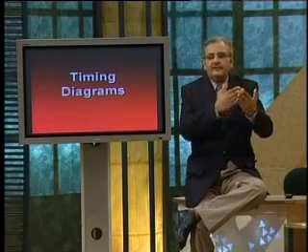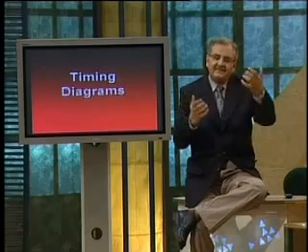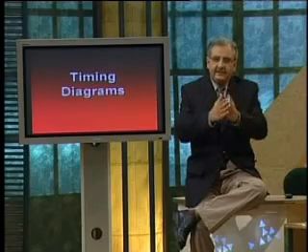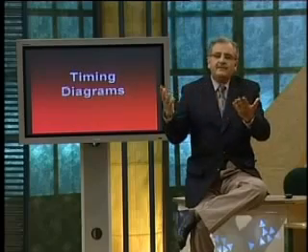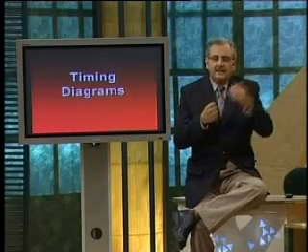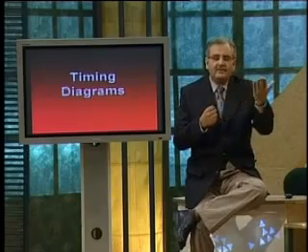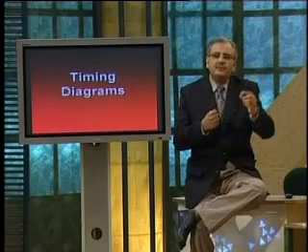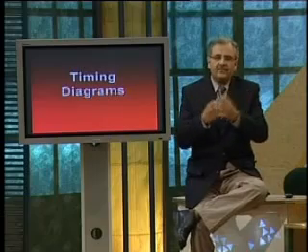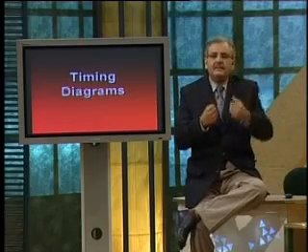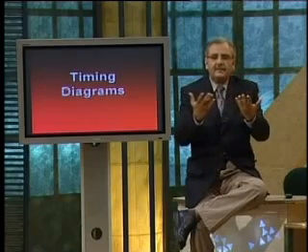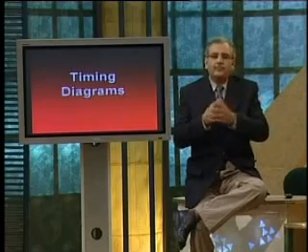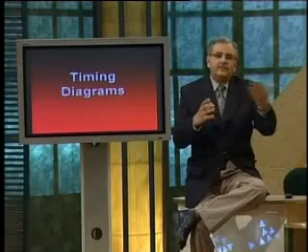For different time intervals, we can see the different outputs, the intermediate outputs and the inputs, and we can verify the operation of the circuit. The other thing we saw in this diagram was that we used the product of sums implementation of the circuit, and we applied the different inputs, and we determined that the product of sums circuit does give you the appropriate output. So it is equivalent to a sum of products circuit.